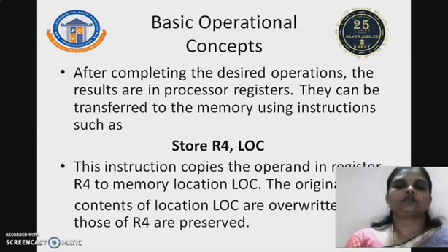After completing the desired operation, the results are in the processor registers. They can be transferred to the memory using instructions such as Store R4, LOC. This instruction copies the operand in register R4 to the memory location LOC.